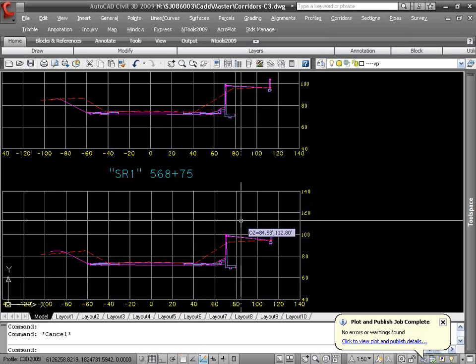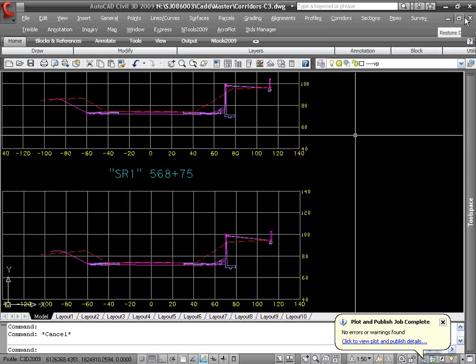Okay, well, cool. A couple of things helping Dion out, just issues that we ran across in terms of editing the assemblies. You've got to really watch. You cannot use AutoCAD move and copy commands to move pieces of the assembly around, because we ran into a couple. I'm not really sure how they were constructed, but when we deleted internal sub-assemblies, if it was built right, it should close the gap and heal itself.